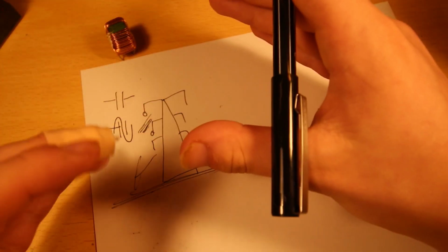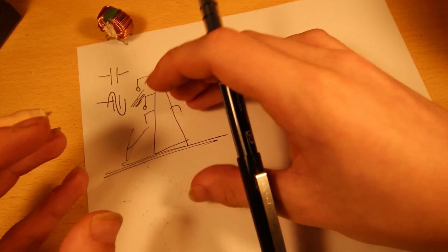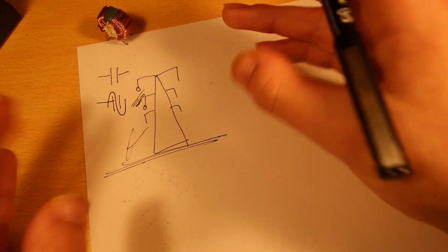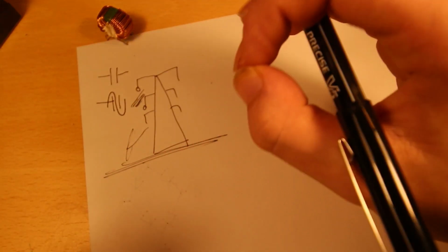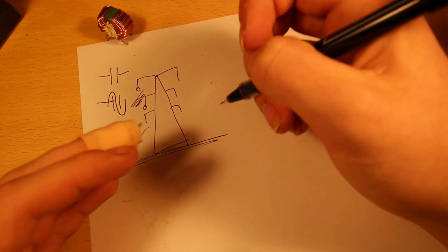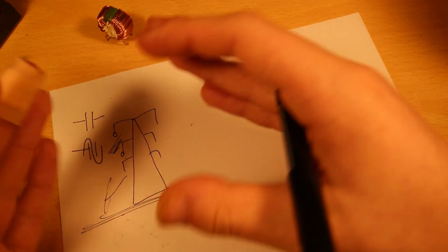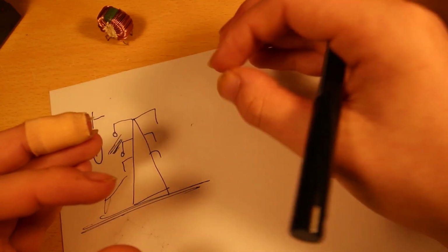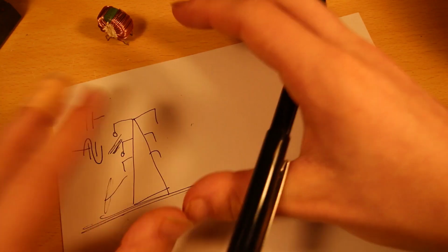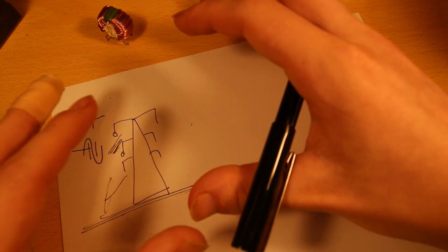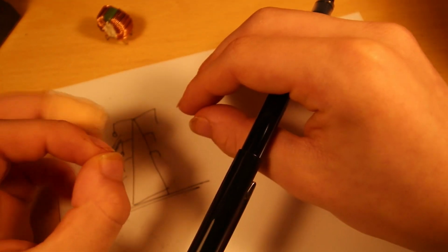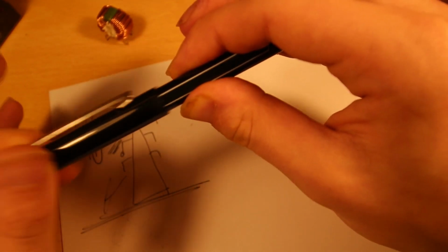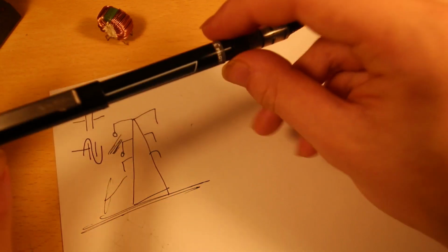Inductive and capacitive loads also cause problems with a thing called power factor. So how I mentioned before that there's magic with substations you can do to turn 3-phase into 12. I will not go into details of how that works because it's extremely complicated. But basically an inductive load or a capacitive load will cause a lead or lag in the current draw as opposed to the voltage waveform. Don't worry if you didn't understand a word of what that means, because it doesn't matter, but basically what that means in practice is that the current flowing to the load is more current than the load actually uses. This sounds very illogical, like it doesn't make sense, but just trust me.